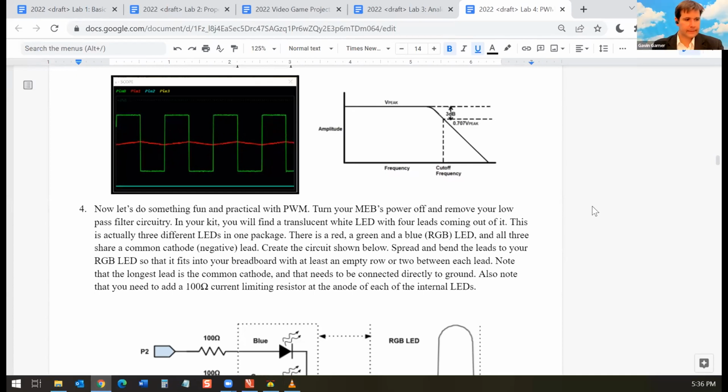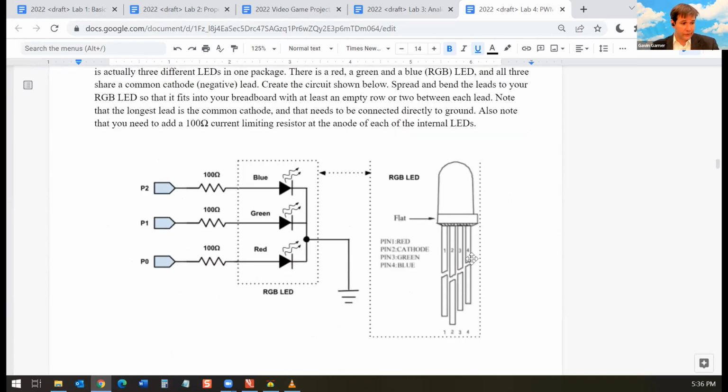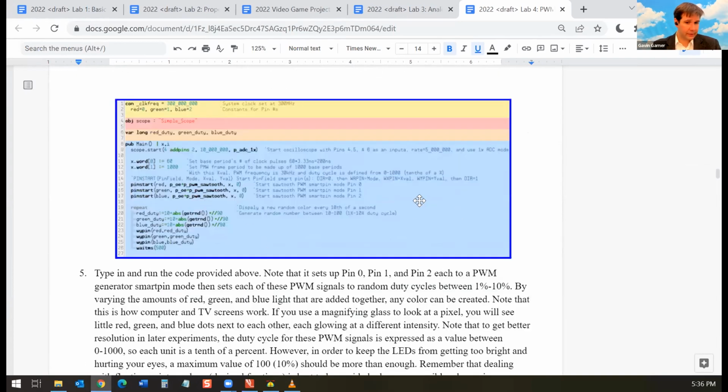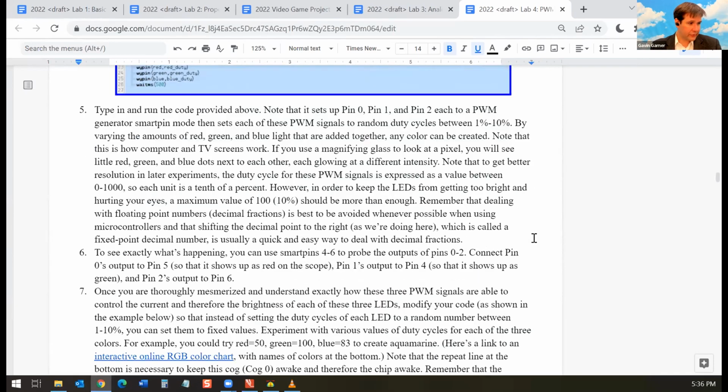I see. Interesting. All right, so other things I showed off is an RGB LED. This is non-addressable, but they send PWM signals into it, so it shows them an application of PWM. They make their RGB LED turn into any color they want by adjusting the duty cycles.